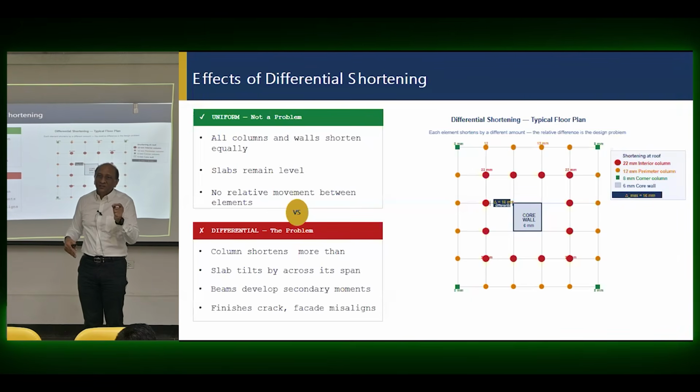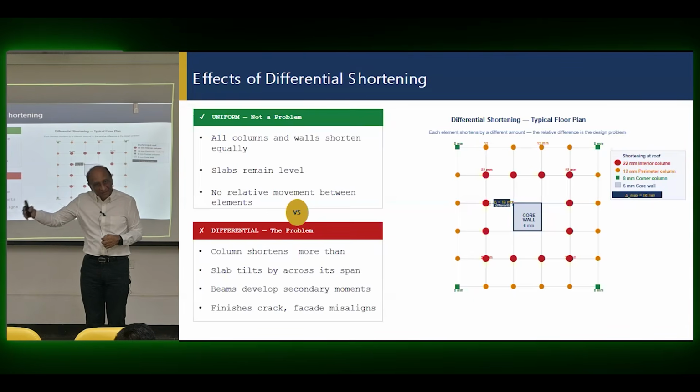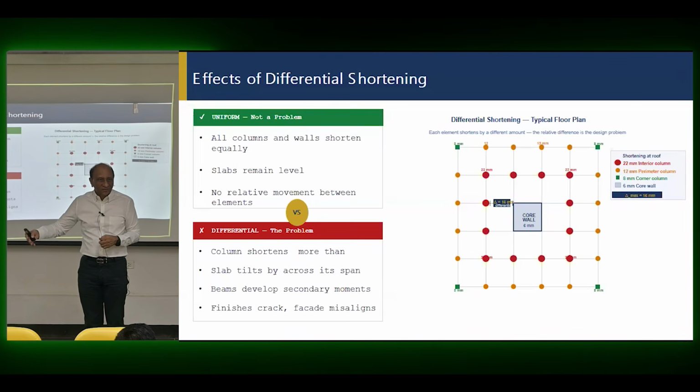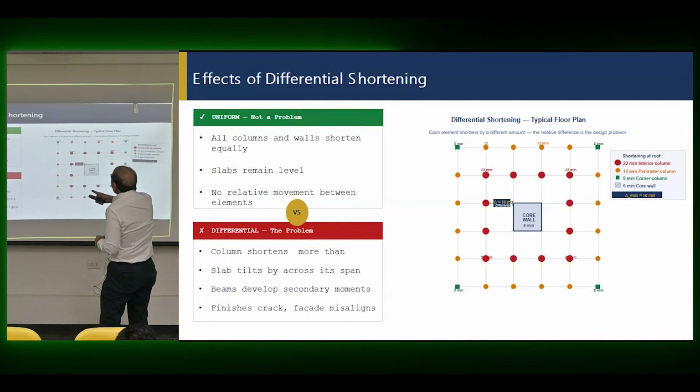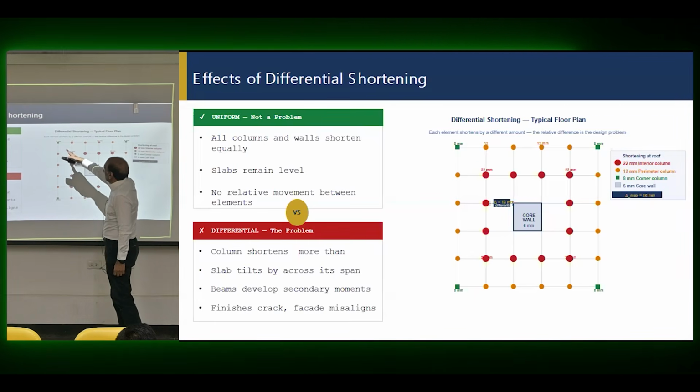So it's not just construction sequence in the way things are made, but after they're complete, what happens to them in 10 years, 5 years, 20 years? That's it, long-term analysis, another step in construction sequence. Under construction and post-construction. So because of that, you can see here that the settlement in different columns will be 22 millimeter, 8 millimeter, 12 millimeter.